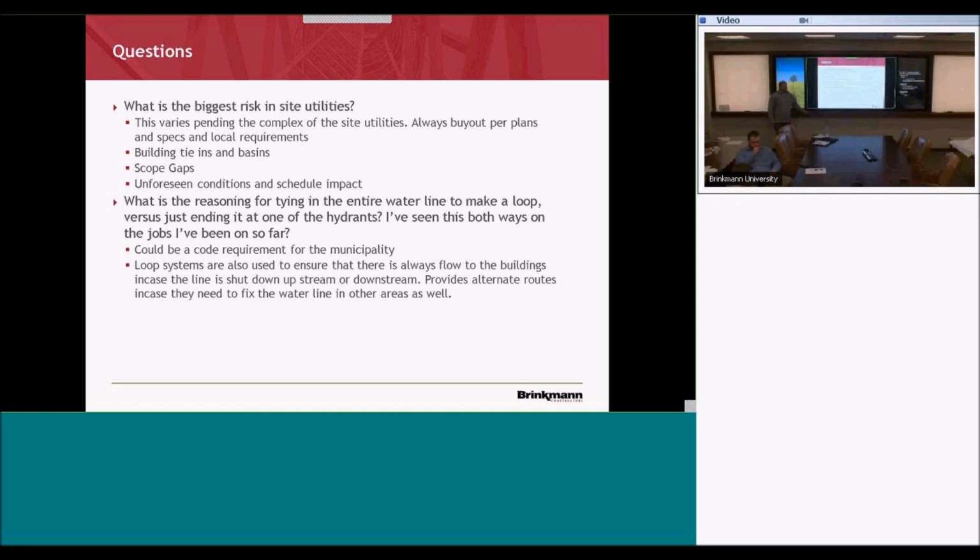The backfill could be rock if it's under pavement, or it could be earth if it's under a green field, and it could be 5 feet, or it could be 18 feet. So just know that when you're estimating that, you can't just grab $35 a foot and say, oh, that's an 8-inch pipe, that's the number. There are still variables that apply to that unit cost.